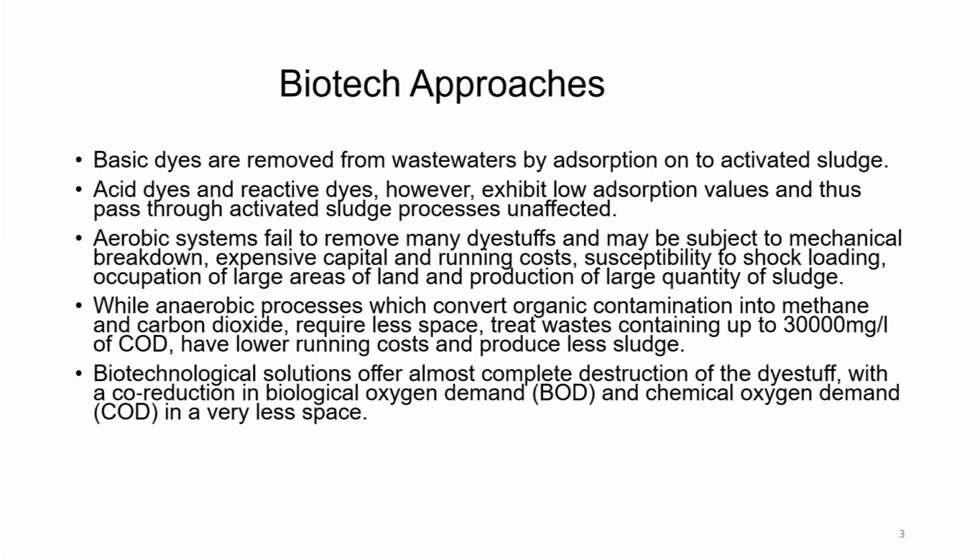Biotechnological solutions offer almost complete destruction of the dye stuff with the co-reduction of biological oxygen demand, that is BOD, and chemical oxygen demand, COD, in a very small space. So, one advantage of using biotechnological solutions is that BOD and COD are removed or lessened, and the space requirement for that equipment is very small as compared to the aerobic one.